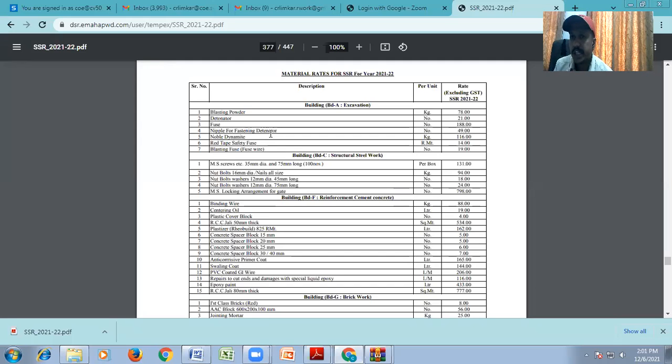Whatever the construction materials we are using, you have to do the market survey for that construction material. Now, what is market survey? You are going to visit some distributor office or some dealer office, and you are going to take the rates of the construction materials. It may be your cement, sand, coarse aggregate, steel reinforcement, plastic pipes, HDPE pipes, plumbing material. Whatever the construction materials that we are having, we are going to take down the rates of that materials.